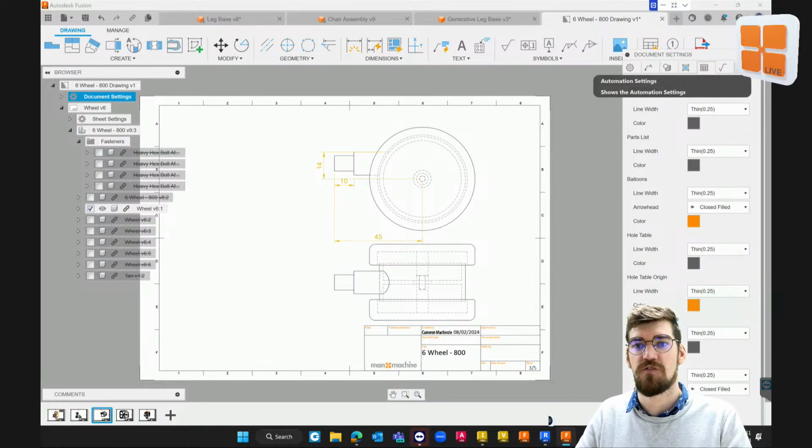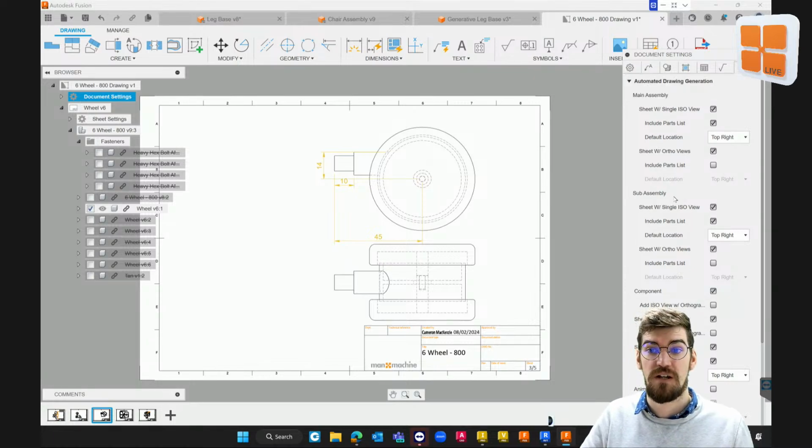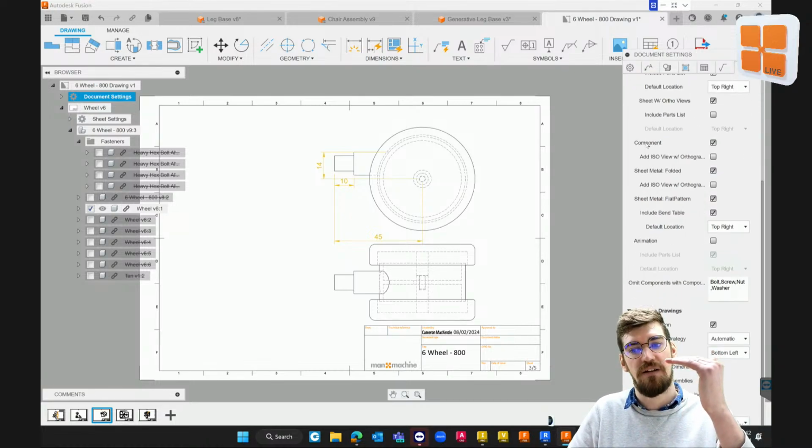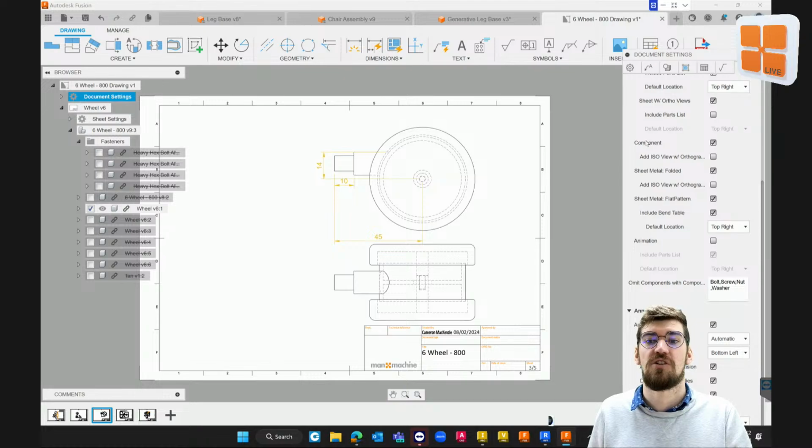And they've now also introduced with this recent update the ability to choose what happens with our automated drawings. So when these automated drawings come in using a template file or using a particular document setting, we can fine-tune exactly what needs to show up, when it needs to show up, and how that particular annotation object does need to show from within there.